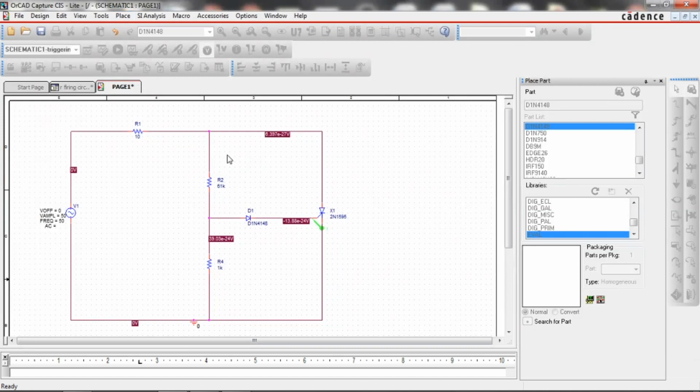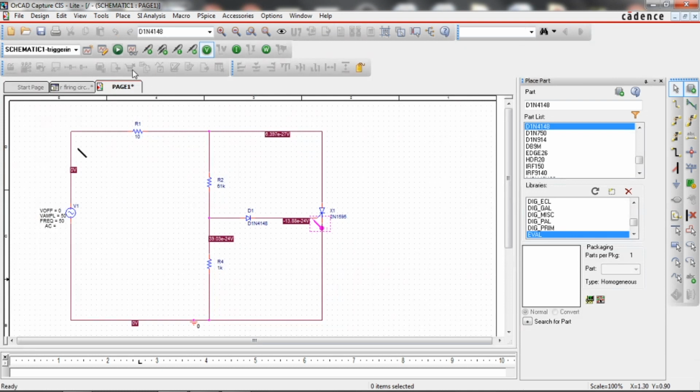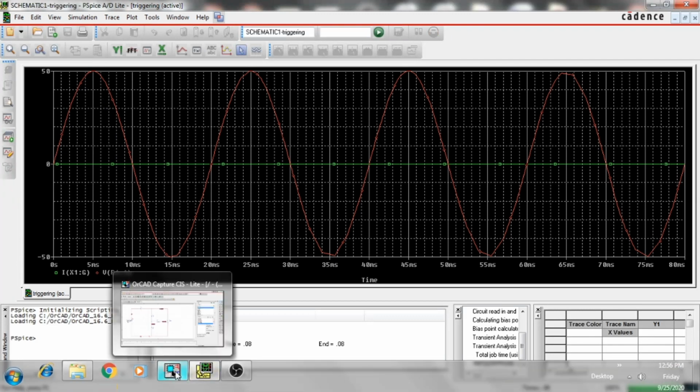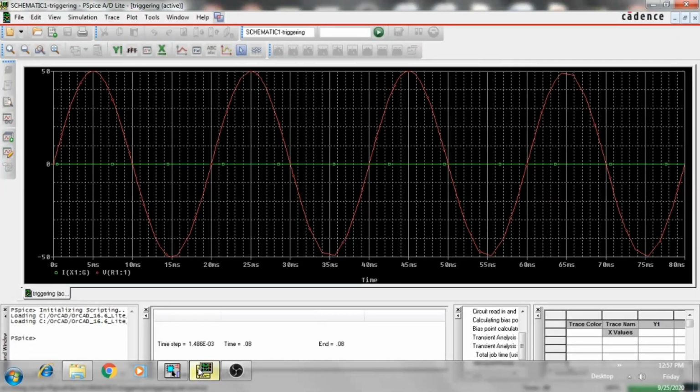So you can see here, if I connect this input, see here, the input takes its peak at 90 degrees, and from 90 onwards it is decaying. So if you increase the resistance, what happens? My intention is, what happens? The current will not reach that value, because after 90 degrees the input is reducing. By Ohm's law, when the input reduces, the current also should reduce. So there is no point of reaching the value which is required.